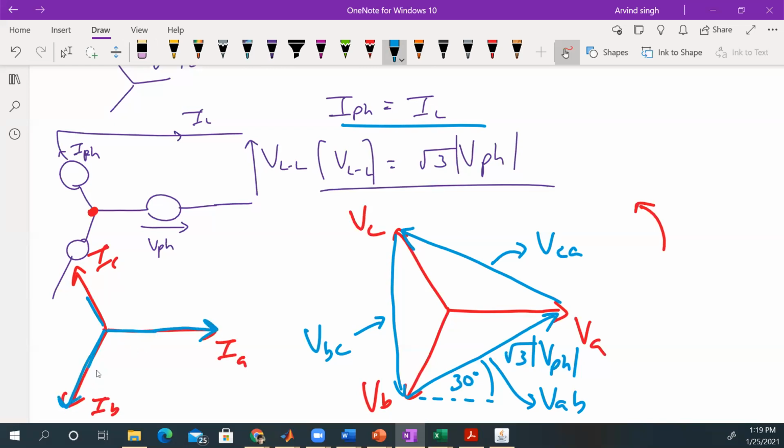So it is exactly the same, right? So the line and phase current are perfectly aligned. They're exactly the same current, because it is the same current that is coming up through here and going through here, right? The only difference is that at this point we call it the phase, and at this point we call it the line, but it is the exact same thing, right?